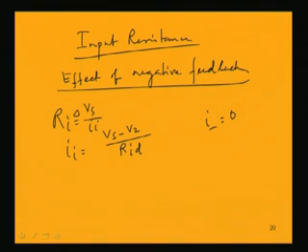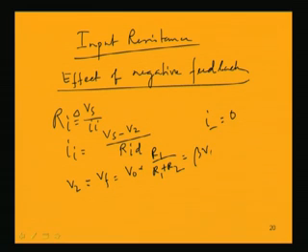So, we get I equal to this, and what is V2? V2 is equal to the feedback voltage, V0 into R1 by R1 plus R2, and that is nothing but beta times V0, because this part is beta. So, now we can write that beta V2 is equal to beta times V0.